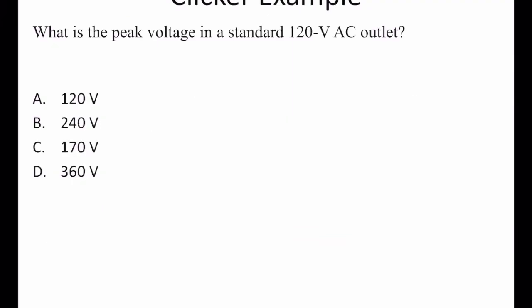When you plug something into the wall, we always say that it's 120 volts, but you now know that it's an AC. So what is the 120 volts? It's fluctuating all the time, so what do you mean that it's 120 volts? Well, the answer is that the 120 volts is actually the RMS value of the voltage that the mains is providing. So the mains is providing a sinusoidal voltage, the RMS value of which is 120 volts.